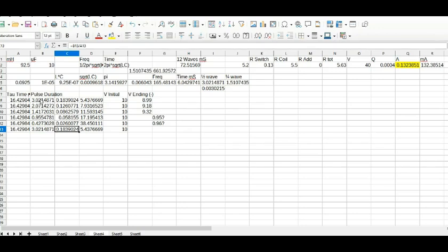So in other words, when you do a briefer pulse, you're of course going to get a weaker magnetic field, but for the amount of charge that you expend to get a given magnetic field, you make more efficient use of your coulombs of charge as you go faster. And that has to do with the equations for instantaneous amp flow. And you can go on a site like Electronics Tutorials, look up those equations and put it in a spreadsheet and see that that's true.